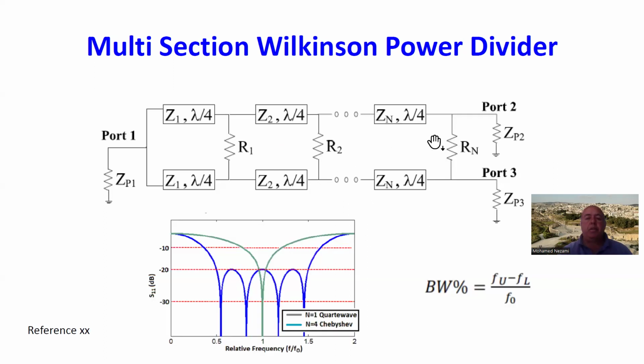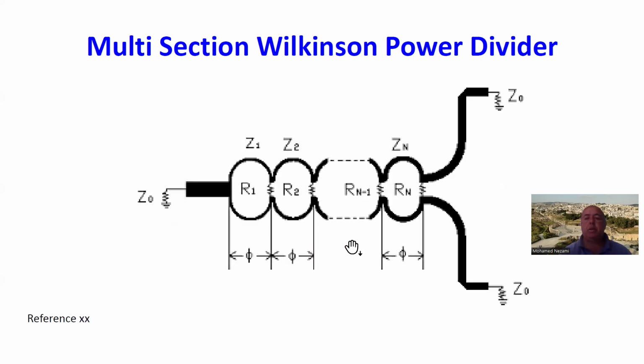The layout of this is usually done like this, where we use the rounded implementation. We come in with 50 ohm, the output is 50 ohm, and we might have a divergent line like this with 90-degree bends so that we can spread it out, connect connectors easily, and get access to this.